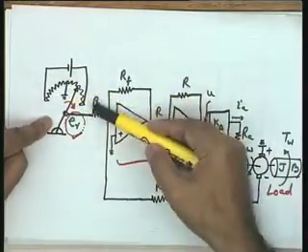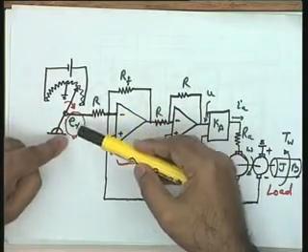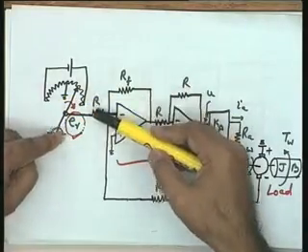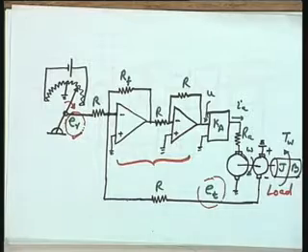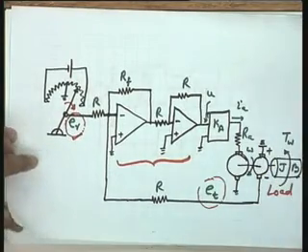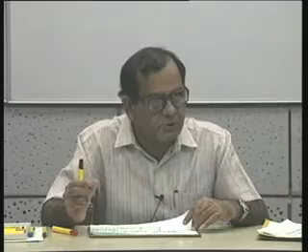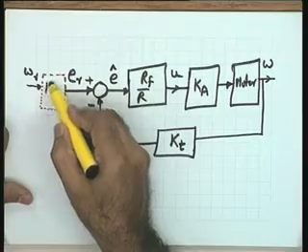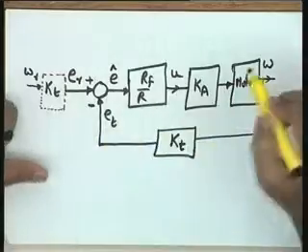You will design this in such a way that the Kp, the potentiometer constant which you get, equals Kt, the tachometric constant, so that in that particular case the error in volts is directly proportional to the error in radian per second, the error in speed. So, therefore, the reference input elements, this is what I want to convey, may or may not be physically present in this system in that form.